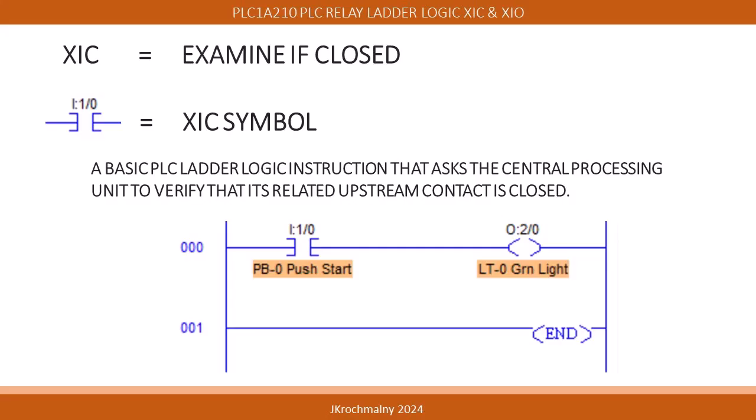Just like drawing a typical electrical ladder diagram, the PLC relay ladder logic contains the same rules: line devices to the rung's left side, and the load devices to the rung's right side. Just like typical electrical ladder diagrams, the PLC relay ladder logic can have line devices placed in series, parallel, or any combination thereof. As per loads used in PLC relay ladder logic instructions, only one load per rung is going to be allowed.